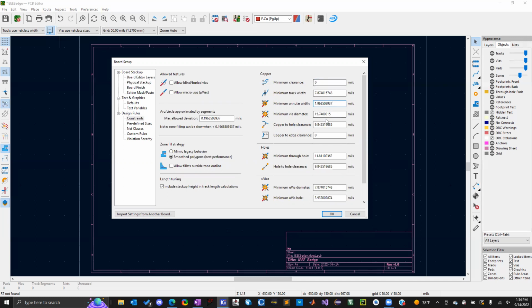And so you can set all those pre-made distances ahead of time. And it's important that you do this because then when you go to actually create the connections for your board, the software won't let you get that close to a through hole component or a via.